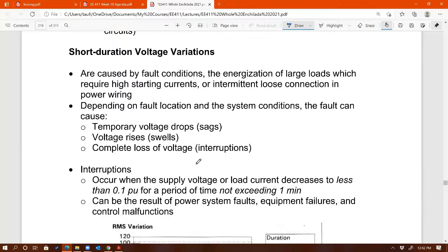Yeah, that would depend, right? I think you said it correctly. That would depend on the size of the electrical system. If you have a single phase induction motor, like in your house, and it's drawing 30 amps quickly, that's going to affect the voltage in your house. That's a local electrical system. You know, it's a weak system.